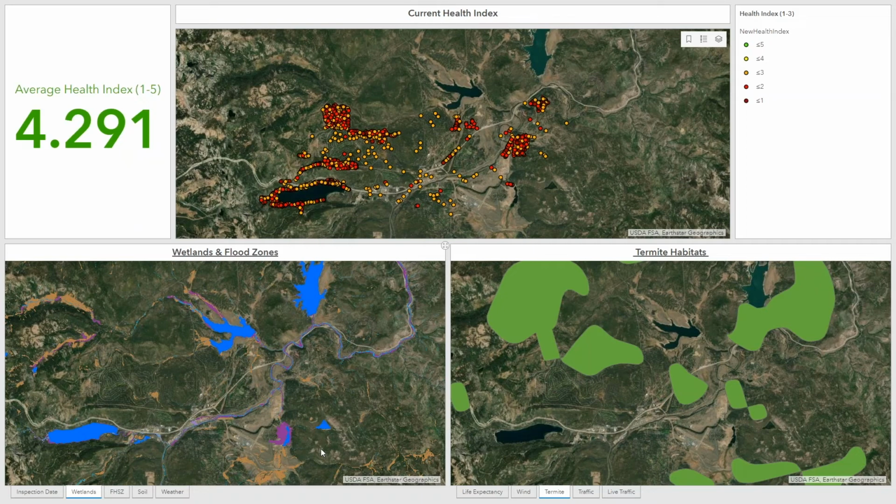So it doesn't really matter how much you do in a termite zone. If you put a wood pole in a heavily populated termite area, short of preventative maintenance, putting a lot of termite poison in the ground, you're probably not going to be able to prevent a lot of damage to your poles. You're going to have to change your design to steel. Does that make sense?